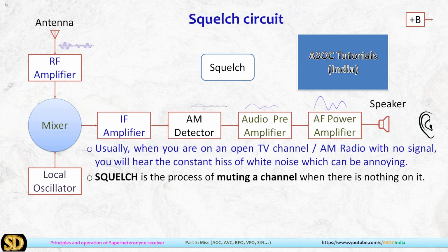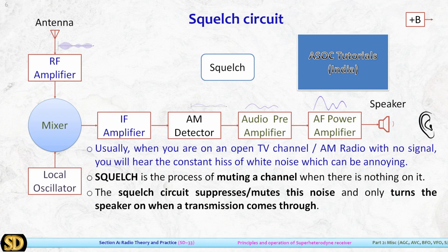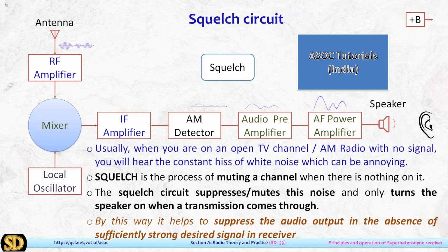Squelch is the process of muting a channel when there is nothing on it. Note it down, later I will ask a question on it. Squelch is the process of muting a channel when there is nothing on it. The squelch circuit suppresses or mutes the noise and only turns the speaker on when the transmission comes through. It means it will respond when there is a strong signal but not respond when there is a weak or noisy signal. This way, it helps to suppress the audio output in the absence of a sufficiently strong desired signal in the receiver.